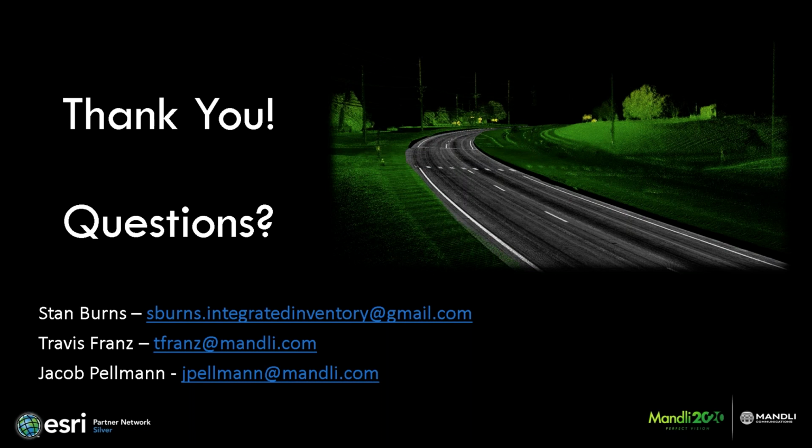Well, for the County of Hawaii, a lot of the way that we broke up some of the sections was based on known or perceived maintenance of the section. We'd often use the right-of-way imagery as we went through, and also the distress information to help determine where we should make those sections. Long story short, if it seems that some agency is maintaining the intersection differently than the roads coming into it, then we would break it into its own section. However, if that didn't seem to be the case, then it would just be lumped into the rest of the section that was already existing. So hopefully that helps answer that question.